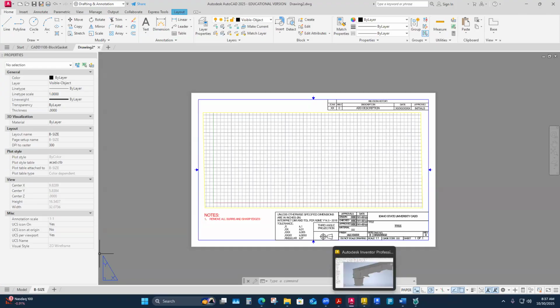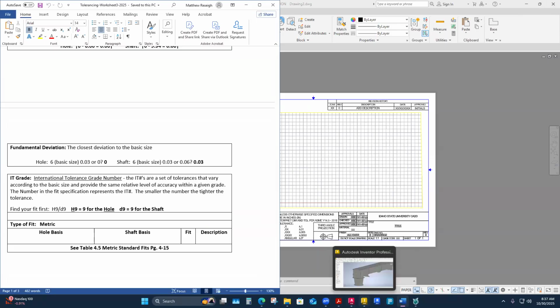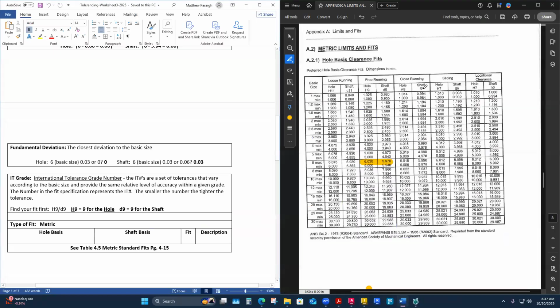Yeah, I think they always use lowercase ones for the shaft. I think it's like a quick indicator. I'll pull back up my data sheets, but I think the large capital letter is for hole designation, and then the smaller one is shaft. So I think it's an indicator, when you know those kinds of codes, that the hole is larger than the shaft. I guess so, right?